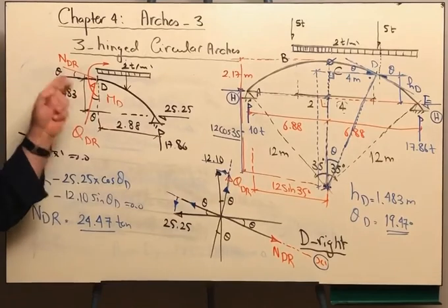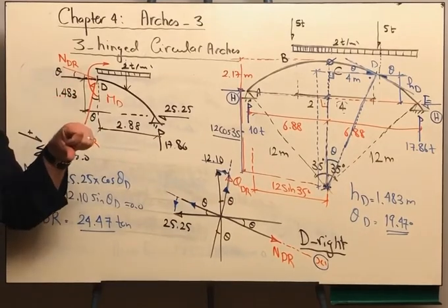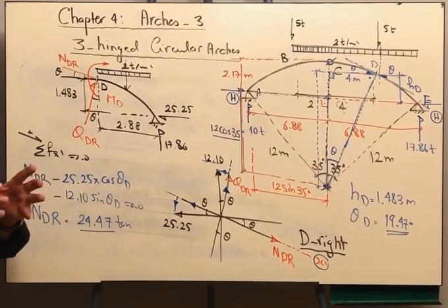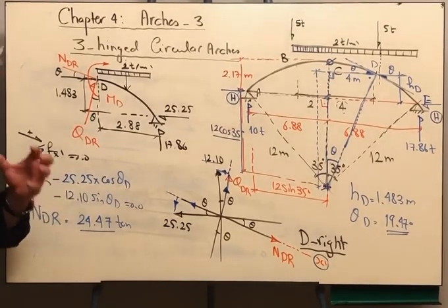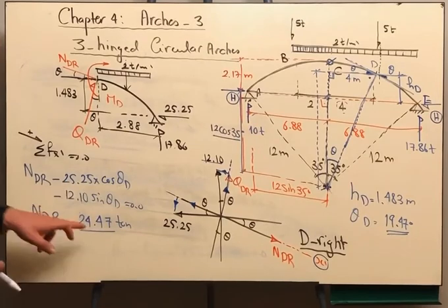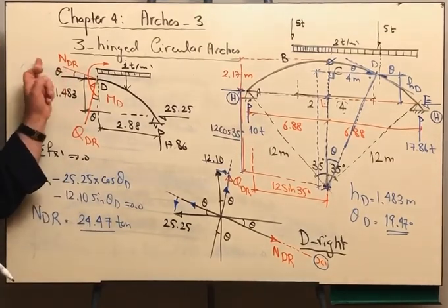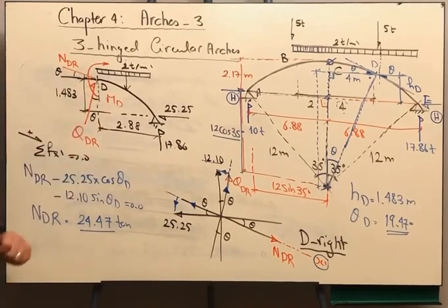which means that it is confirming that the internal force is compression. The internal force in the arches cannot be tension, it must be compression. It is positive because we assumed it from the very beginning is compression, and because it is directed towards the section. Okay.